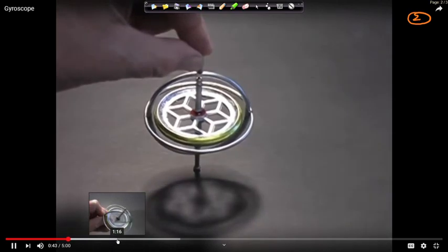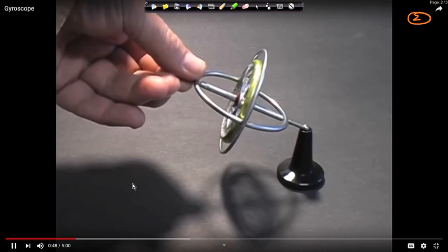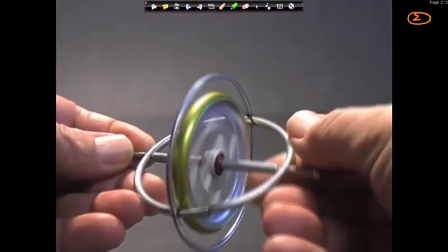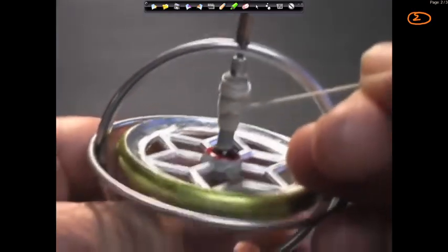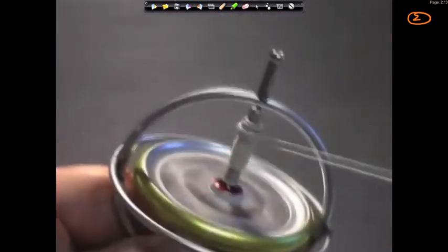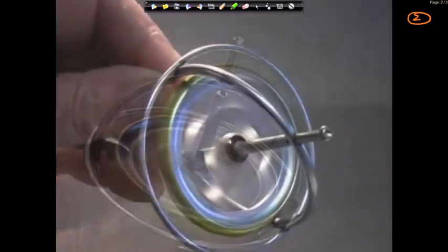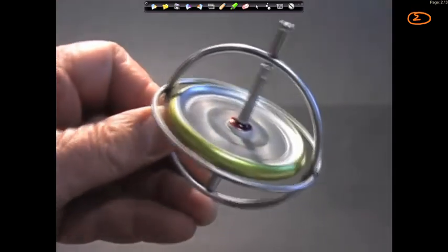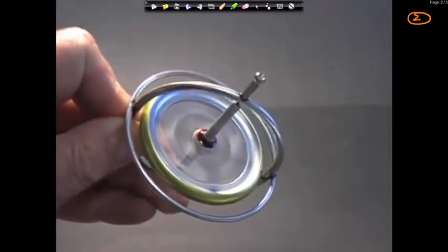Try to stand it on end and it falls over. Normally if the wheel is not rotating and you keep it like this, it will simply fall. Apparently it can defy gravity. But if you spin the wheel, it is spinning about a certain axis and there is angular momentum associated with this, and the wheel tries to maintain that particular direction unless disturbed. In this case the gravitational torque will be acting and will tend to disturb it, and as a result it precesses and nutates.